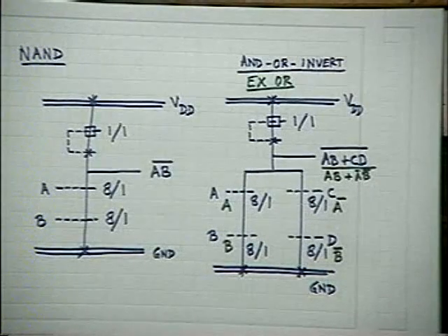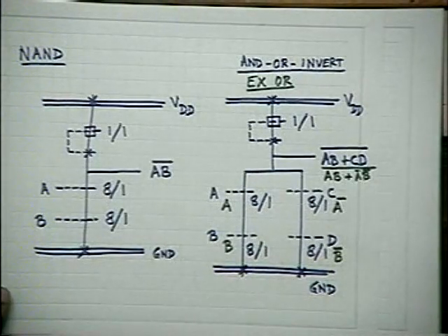Or you can, in the conventional way, also draw A B bar plus A bar B, inverted, but you need another inverter in that case. But for the A bar part, you just write A bar or inversion. You are saying that A has to be inverted, B has to be inverted, but it is normally assumed this is only a part of the whole circuit. So whenever you are applying A, B, C, D at the input, there is always an inverter chain.